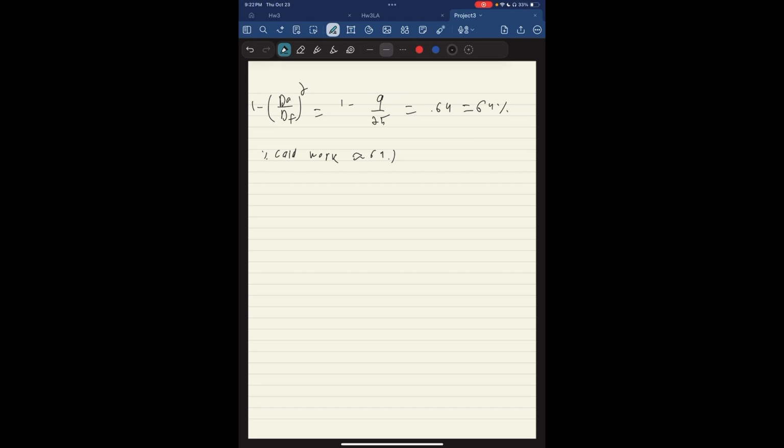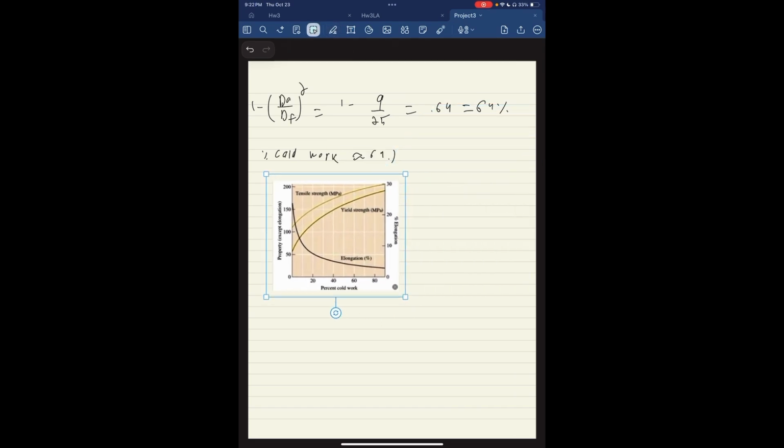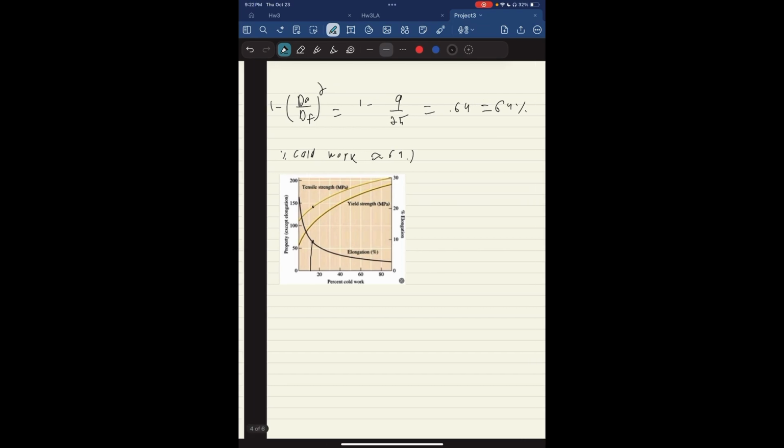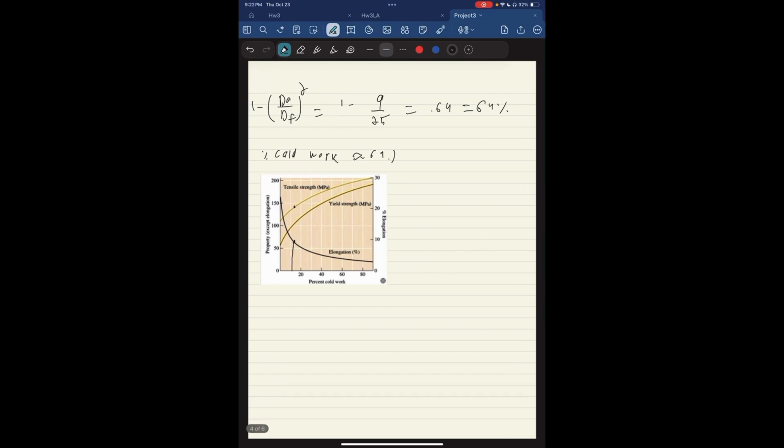And then using this, I can plug in the graph I got for aluminum to find that the final one, if we use the 12% that Reed found for steel to be around here, we get a percent elongation that would end up being around, say, 10-ish percent, and a tensile strength of around, we'll say 130 megapascals. But in order to do that, we have to go through the math first to show how we got there.